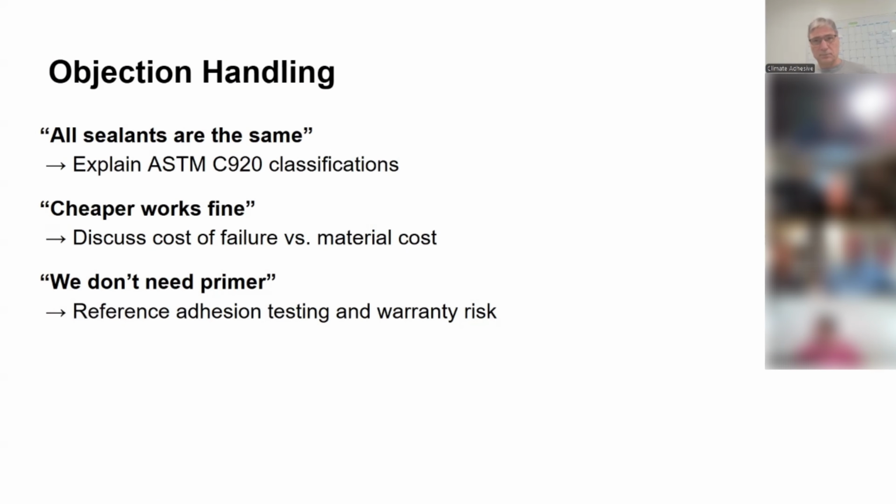But we just went over this with this parking ramp they're building here in Kalamazoo. We're trying to get inclusion into the specification, and we did a presentation with the construction manager and stuff like that. And I had a lot of pictures from parking ramps of failed joint sealants, and then all the spalling that ends up coming as a result of some of that.